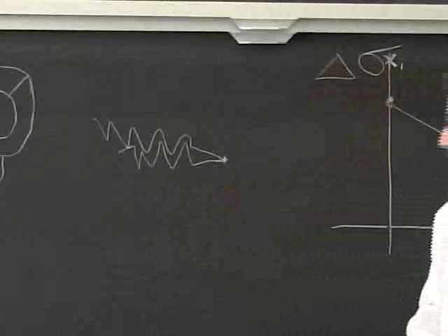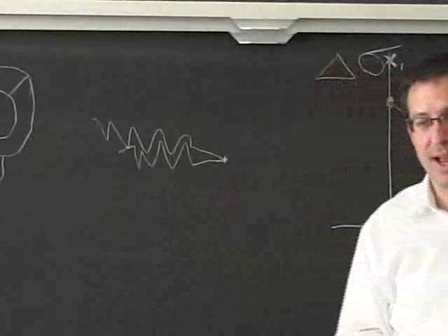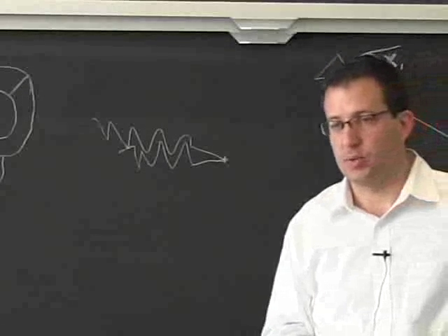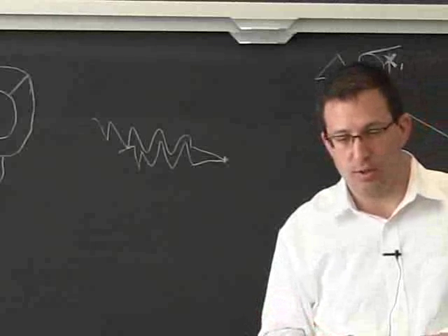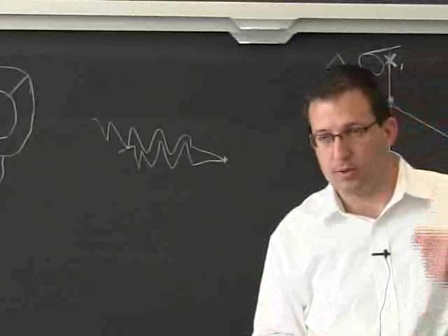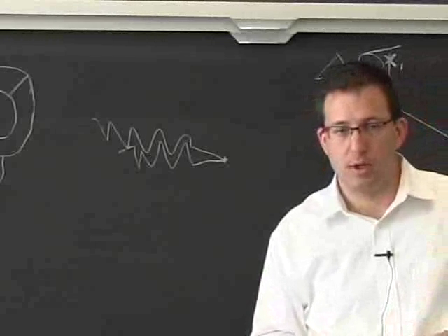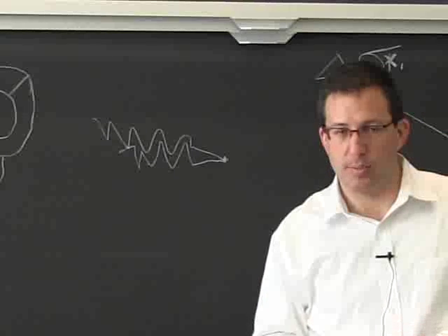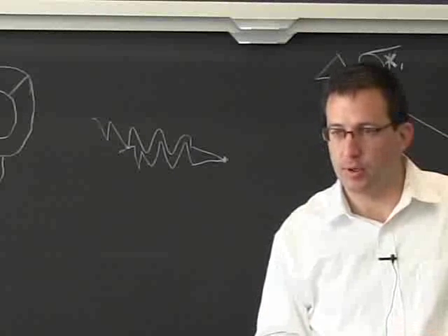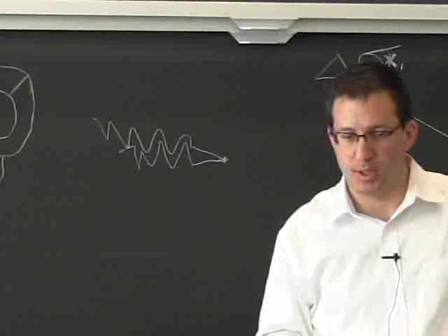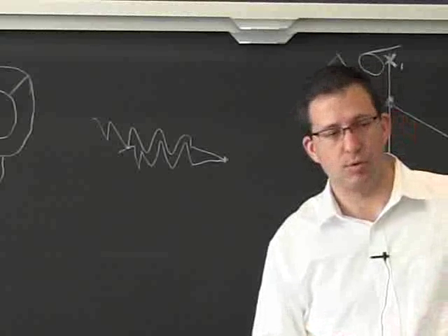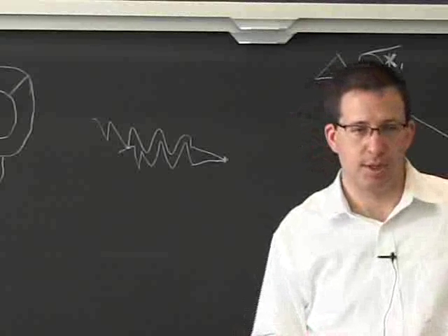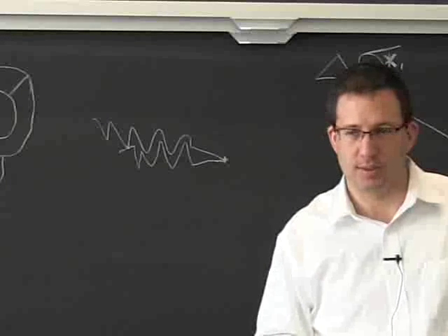For the tension side, you worry about cracking. And that's where I essentially used both the total fatigue curves and also damage tolerance, assuming there was already a flaw in the casting to begin with. And the Paris equation says, is that going to grow to the critical size in 30,000 takeoff and landing cycles.